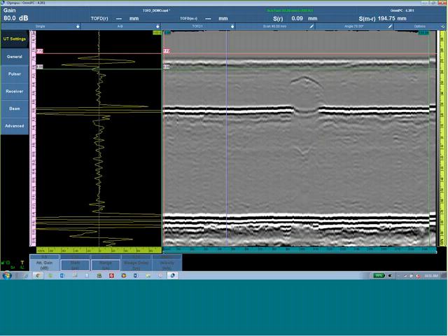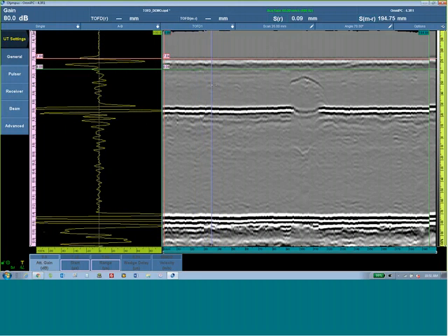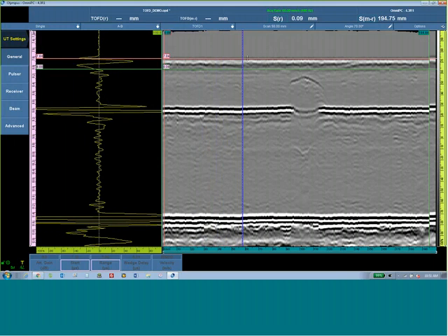Okay, the lateral wave is straightened so that the arrival time is within a fraction of a microsecond for all A-scans. This removes the jittery part of the scanner as it wanders or moves slightly side to side, changing the time of flight.